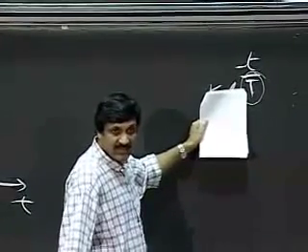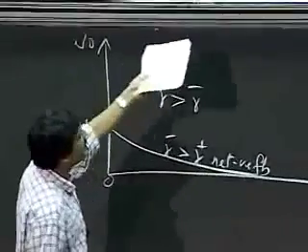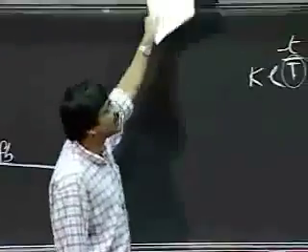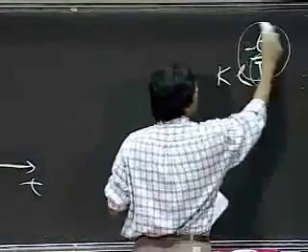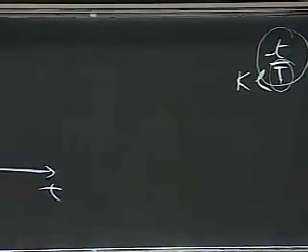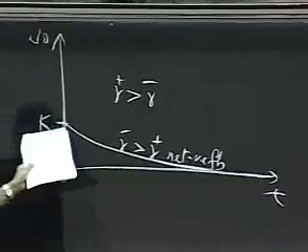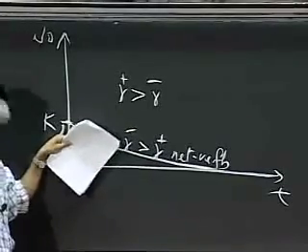Now, we cannot see this happen in an RC circuit because capital T is equal to RC. But here we have a more complicated circuit, and capital T can go negative. If capital T goes negative, then this whole thing in the exponent there goes positive. If that goes positive, what should the output look like? It should go up, it should take off into never, never land.